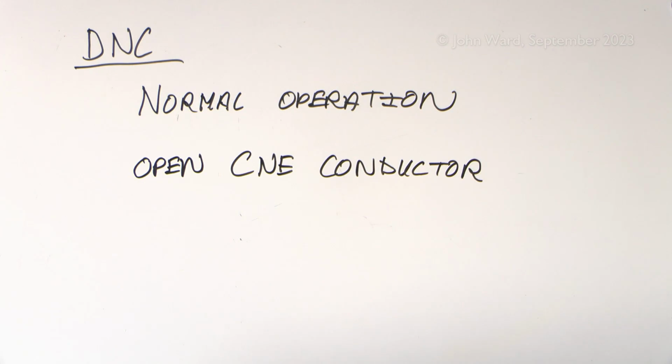In both of these cases you're going to get current flowing via other paths other than the incoming cable, so via bonding and whatever else. So if you're going to go to an installation and disconnect the bonding, first of all you need to turn off that particular installation completely. Of course that's just standard procedure. You don't want to be disconnecting these things when the installation is on, because you're removing a safety feature.